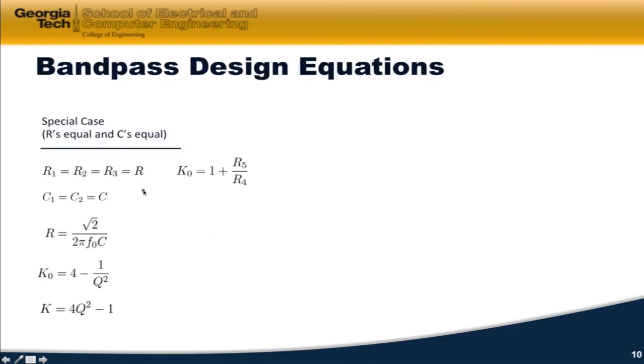I'm just giving you one special case here for the bandpass design, letting all the resistors be equal to each other, equal to a value R, and all the capacitors equal to each other and equal to a value C, and you get these simplified design equations.